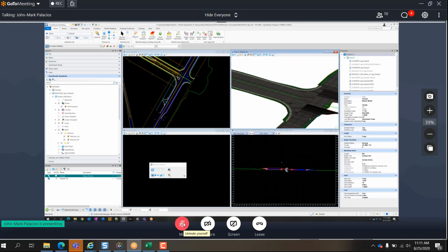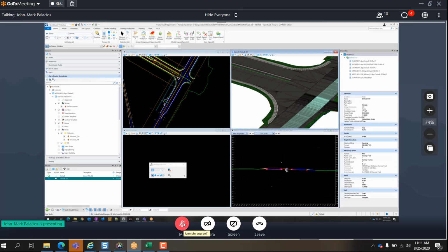Technically for earthwork, there should be a surface at the bottom of the structural core, or bottom of the base rather. My bottom surface. So if I create that bottom surface, I could do the analyze volumes and make sure I had the correct volume there.